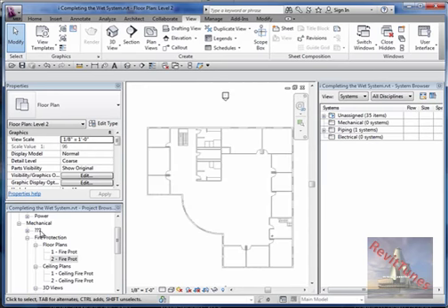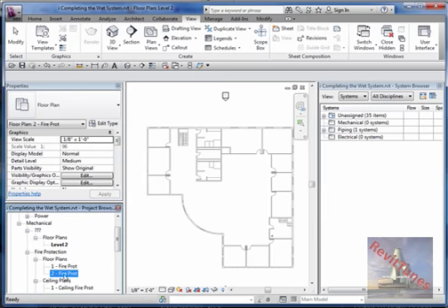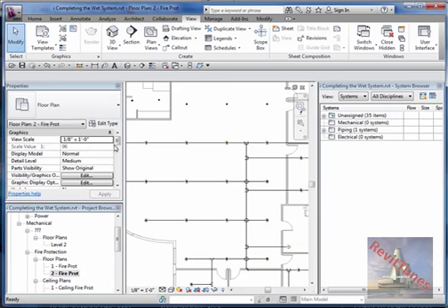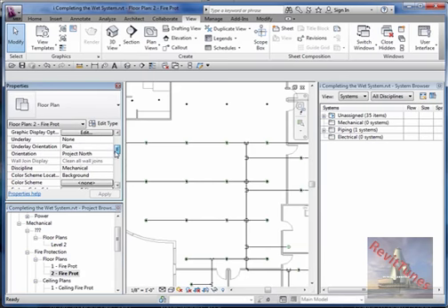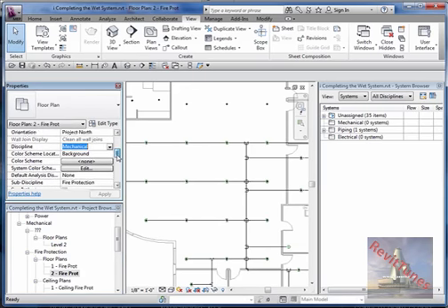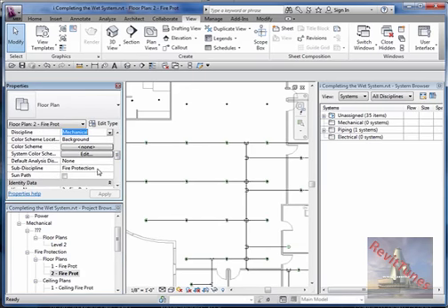but it goes to this question mark section instead of going to fire protection because it still doesn't know what category I want. If I go to the fire protection, you will notice that it says right here discipline mechanical and subdiscipline fire protection.